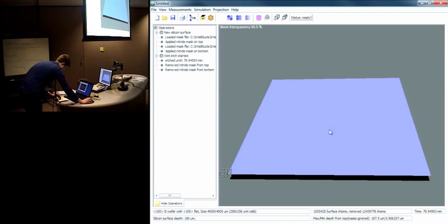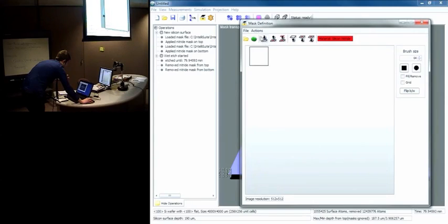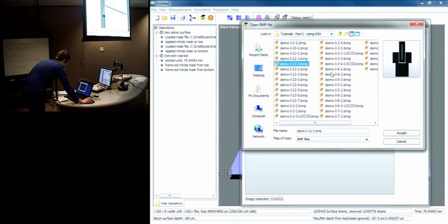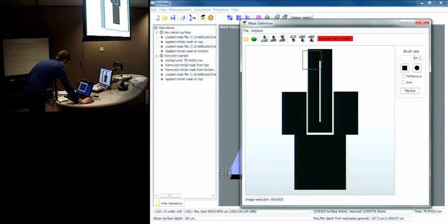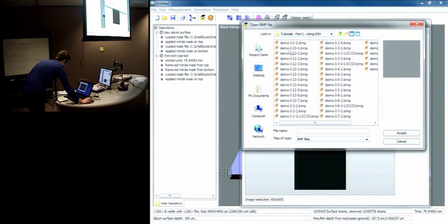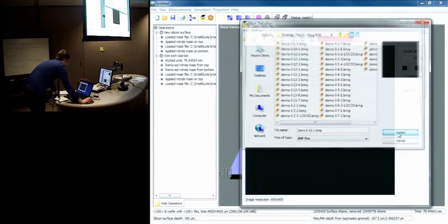Next, we'll apply a nitride layer again and perform another set of etch steps to get our final design. We're making a micro probe in this case. So we can apply this to the top. And to the bottom, we're just going to use the same complete covering as before.